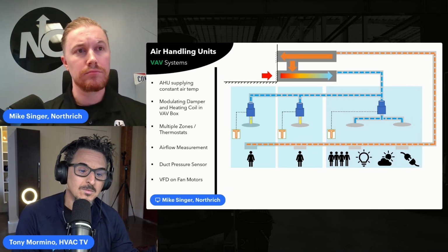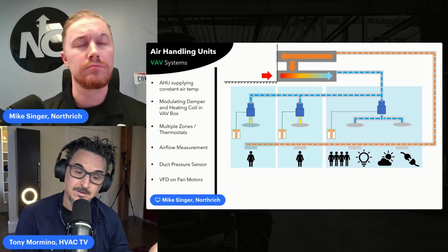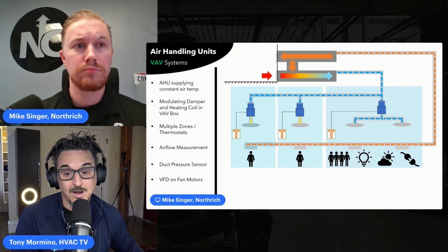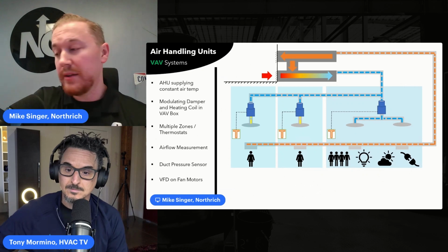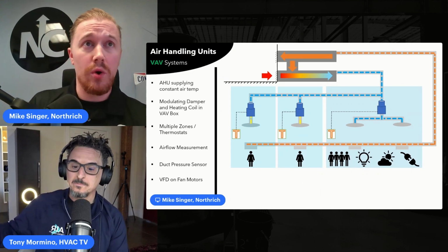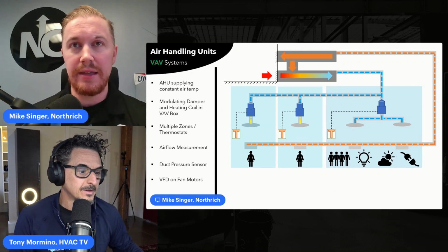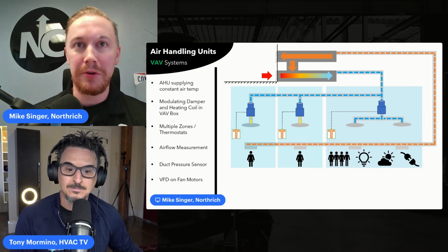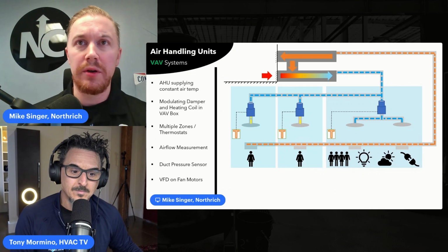So in terms of reheat, it's okay to use boiler water for reheat, or electric heat. I've never had a problem with specifying that. Sure. In Ohio, we will see hydronic reheat quite often. Gas is very cheap here, so we're typically seeing that reheat water supplied through a gas-fired boiler. Right. But yeah, you're correct, and I think that's one important note as well.